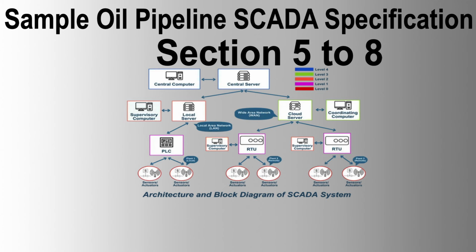6.2 Construction. Marshalling cabinets shall be supplied with Alulux roller doors. The roller carrier impingement into immediately adjacent secondary safety access ways shall be minimized. The lower edge of this carrier shall be rounded off with a minimum accessway clearance height from floor level of 2,000 millimeters. All cabinets shall be supplied with 50 millimeter high channel section frame plinths for pre-shipment to module fabrication yards for welding into position. Shipping plinths shall be supplied for interim use during cabinet manufacture, testing, and transportation.